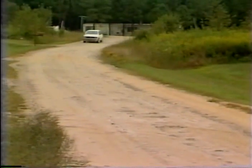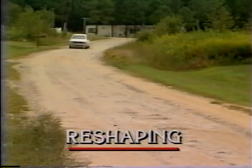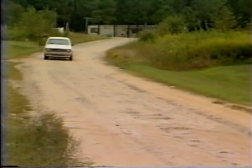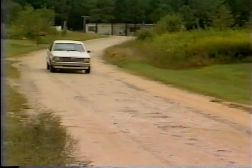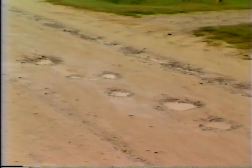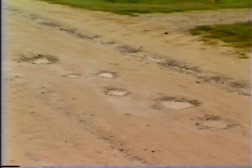The other basic type of gravel road maintenance is reshaping or cutting of the roadway surface. Reshaping is required when the crust of the roadway has deteriorated due to traffic and weather. Reshaping eliminates ruts, potholes, and washboards.